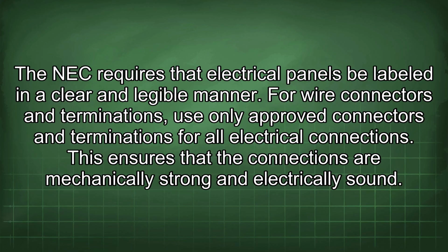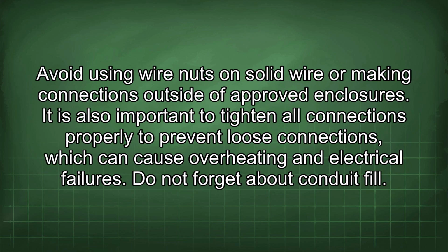For wire connectors and terminations, use only approved connectors and terminations for all electrical connections. This ensures that the connections are mechanically strong and electrically sound. Avoid using wire nuts on solid wire or making connections outside of approved enclosures. It is also important to tighten all connections properly to prevent loose connections, which can cause overheating and electrical failures.